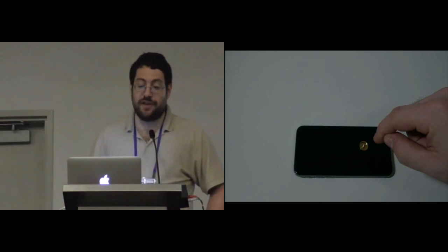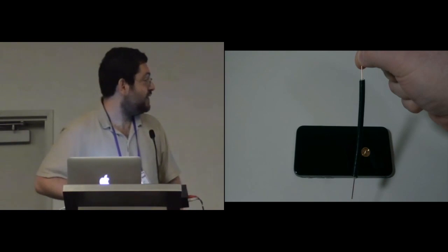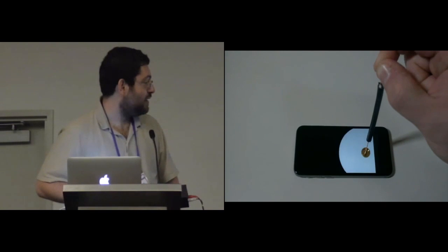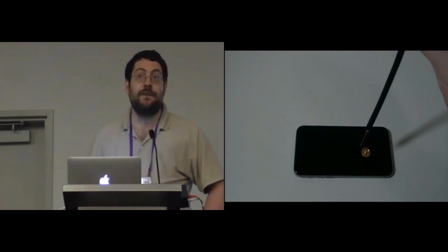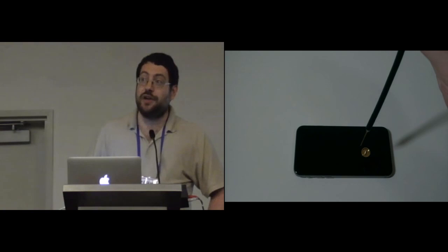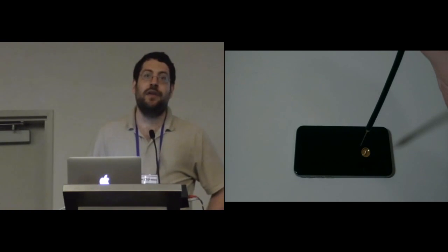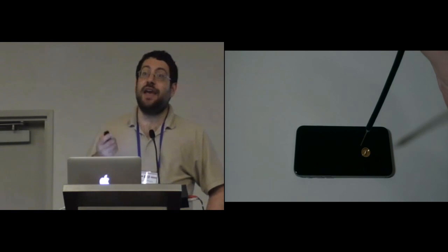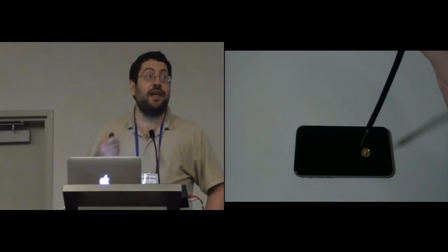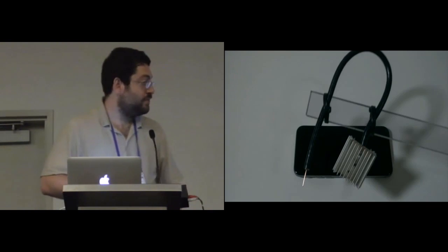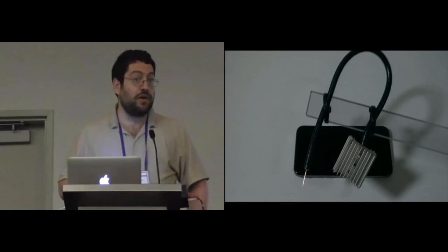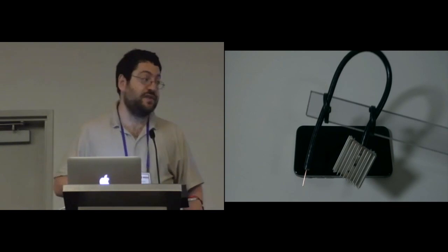Because we're just having it connected to me, I could also connect it via a wire. So here's me holding a wire and tapping it, and it still works. This isn't all that useful on its own because it's still me sitting there tapping it with a wire. But what we can do is use something else to change the charge that's on the screen. If we have something else that'll dissipate electrons into the environment, that'll also trigger a touch. So this is not actually part of the Latency Hammer, but it illustrates the principle.